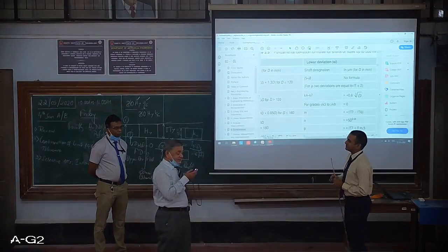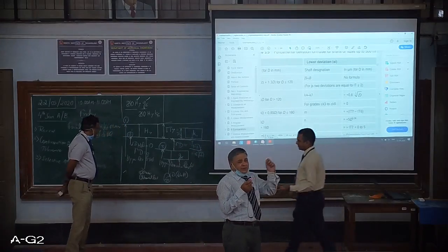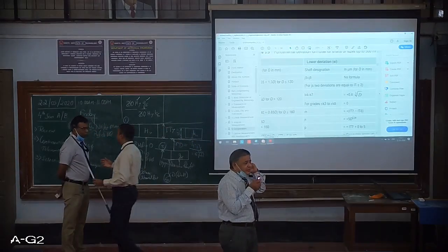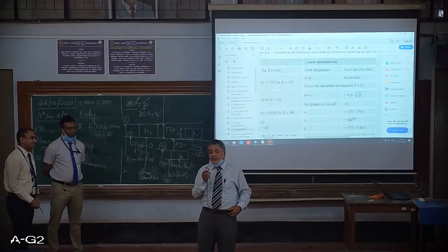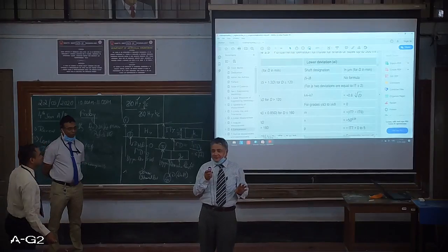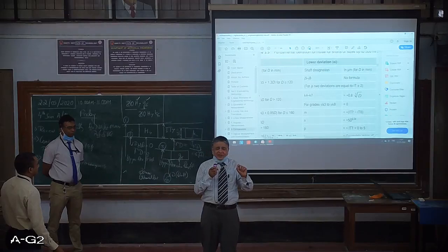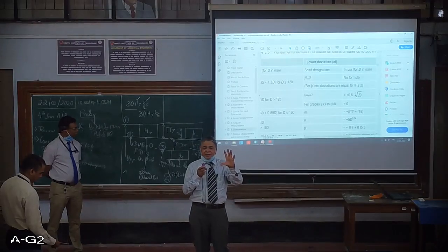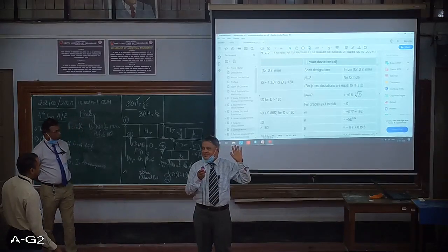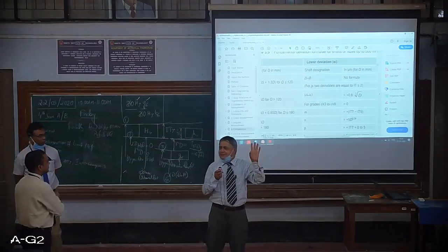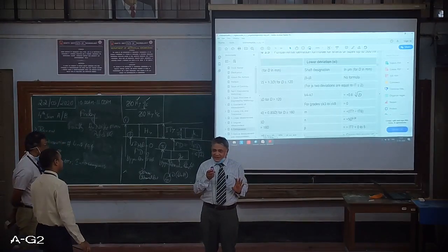Yeah. See, there are two things about that zero line, as we call it, but most of the industry applications say that zero line is the zero deviation line. That means if any component is, say, 40, the zero line represents exactly the 40 basic size. Zero line represents the exact basic size, and from that the deviations are always plotted on one side. That is the idea.